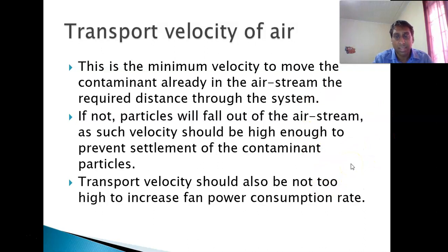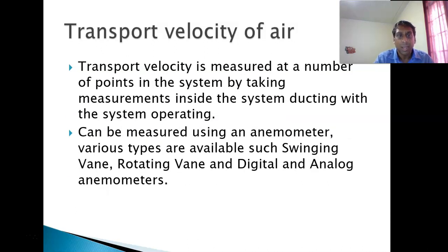Transport velocity is measured at a number of points in the system by taking measurements inside the system ducting with the system operating. It can be measured using an anemometer, and you may want to learn that. Various types are available: swinging vane, rotating vane, digital and analog anemometers. So you can probably learn one or two of them. I've never really seen a question asking how they work.